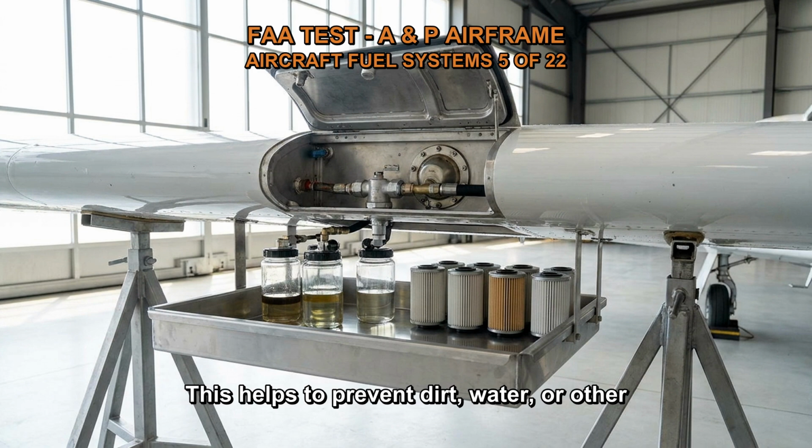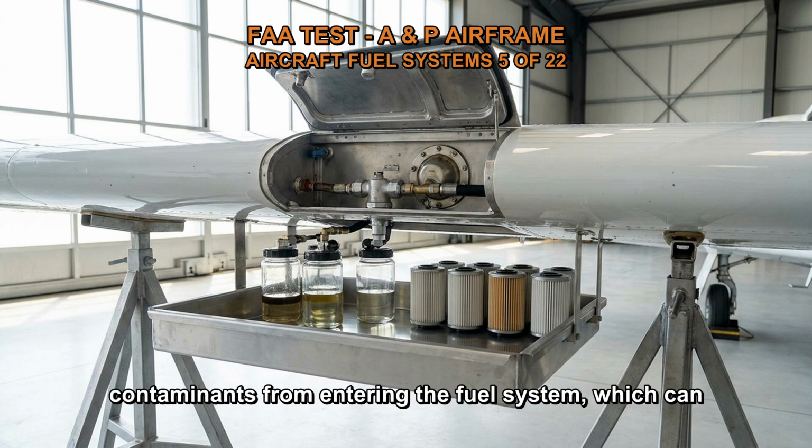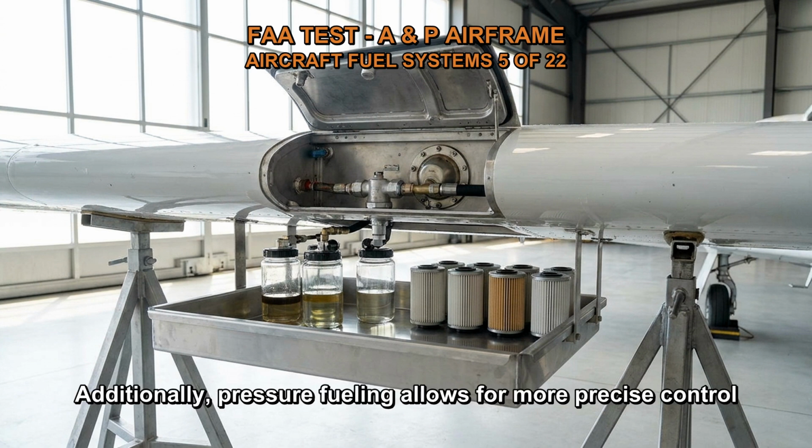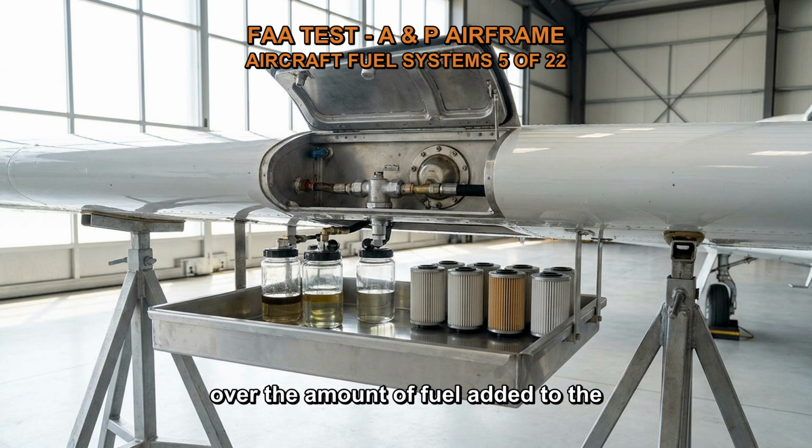This helps to prevent dirt, water, or other contaminants from entering the fuel system, which can cause engine damage or failure. Additionally, pressure fueling allows for more precise control over the amount of fuel added to the aircraft, which can help to keep the aircraft within weight and balance limitations.